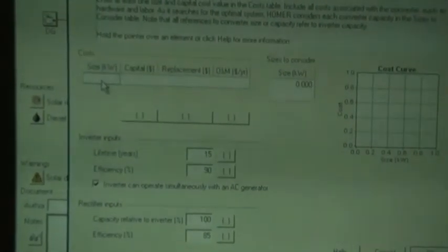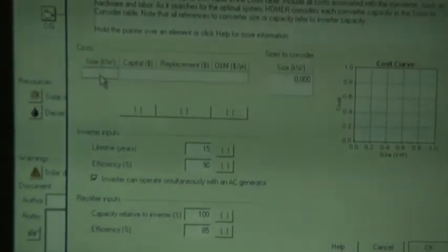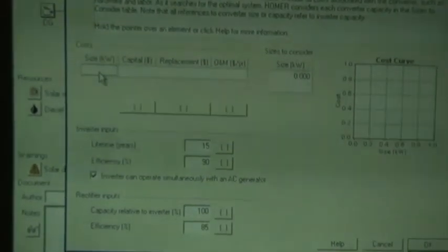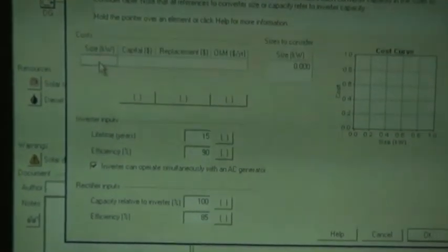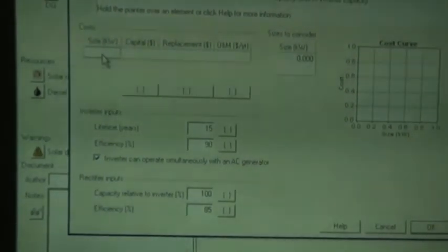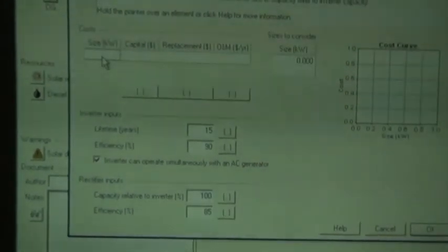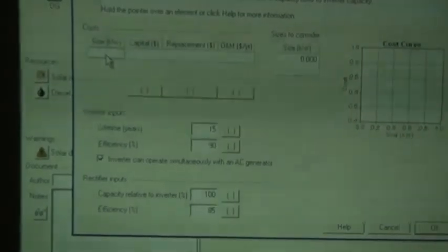So what we will do here is only take the module's cost, and the box cost, that means the cabinet cost of the rectifier, we'll take separately and put it as an additional capex cost. Otherwise, HOMER is a bit naughty here. It takes a linear value, which is not actual and may not be suitable for our overall calculation.